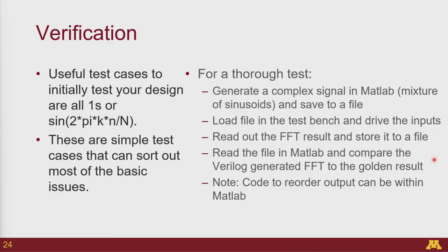So to initially test your design, a very simple test would be just passing all ones to your inputs, or passing a simple sine wave, for example, sine of 2 pi kn. In both cases, you'd want the result such that only one single bin of the FFT has any value and everything else is 0. In the first case, it'll just be the 0th bin. In the second case, it'll be the kth bin of the FFT.